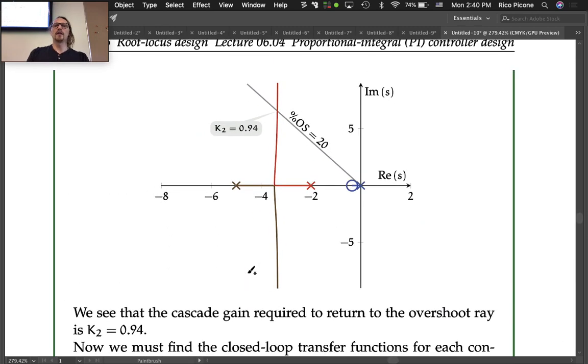Again, we do another root locus. And remember, our goal with this integral compensation was to not affect the root locus too much, right? So it does look quite similar. Obviously, you're going to have a little bit of locus right there. That's always going to be there with an integral compensator because you just literally put a pole and a zero on the real axis. It's always going to have that part. But the rest of the root locus looks pretty much the same.